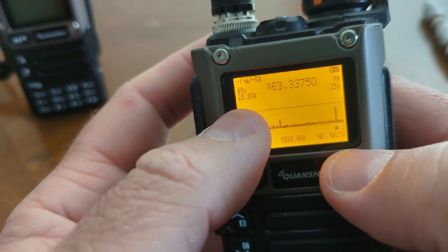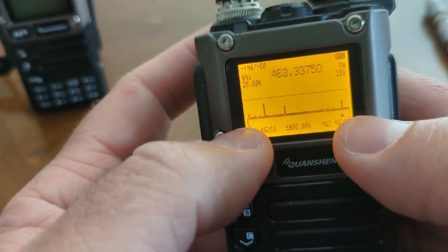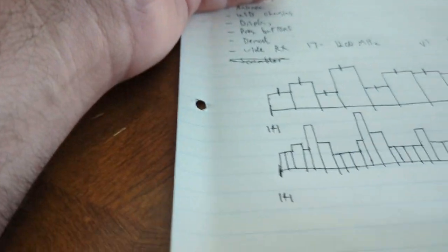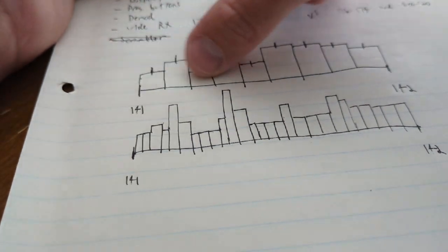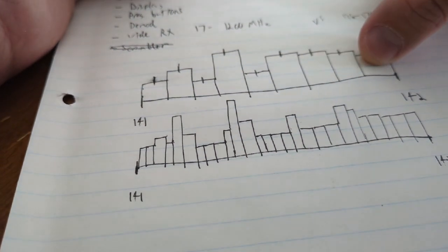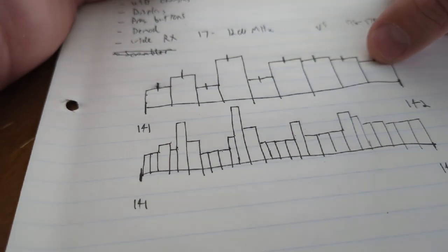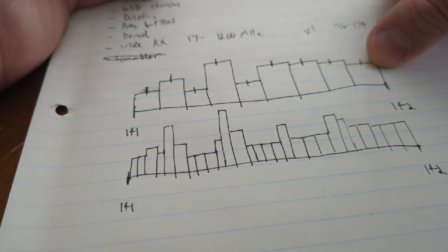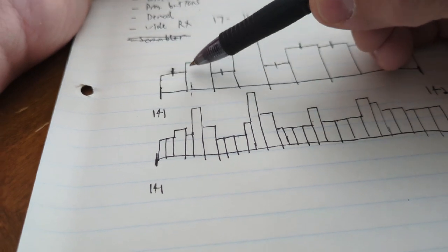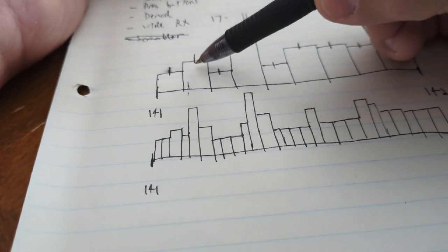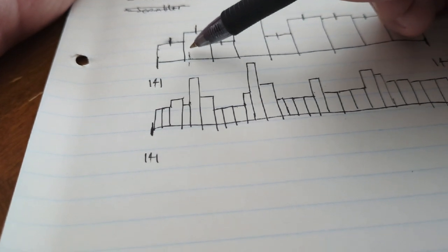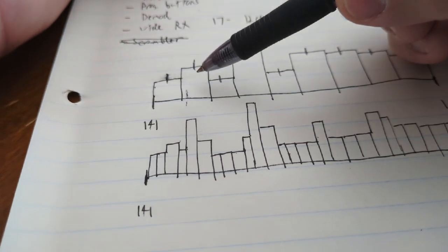Or if I increase or decrease the width of those individual bars, I will listen to a wider or narrower chunk. Say I want to listen to 141 megahertz to 142 megahertz. I can have a relatively small number of bars or bins on my chart, and it'll scan faster, but I get a less detailed view of what's going on. If a signal shows up in a bin, it's going to give me the center frequency of this bin. That's all the more precise it knows. So I might be a little bit off frequency and have to tune a little bit, but I might still detect the signal. It'll just be less sensitive.